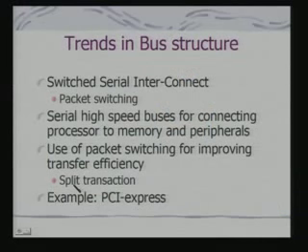We had also discussed the basic concept of split transaction. That means you carry out a transaction, and if my slave is not currently able to do it, it remembers the identity of the master and later on carries out the transaction. This is the basic concept, and it is very similar to that of packet switching.